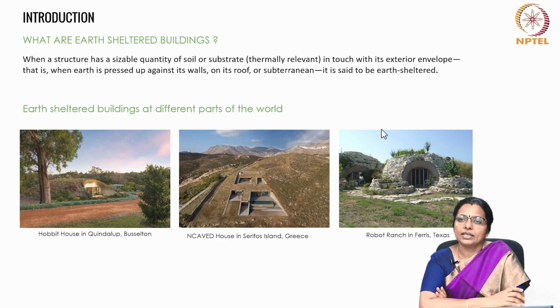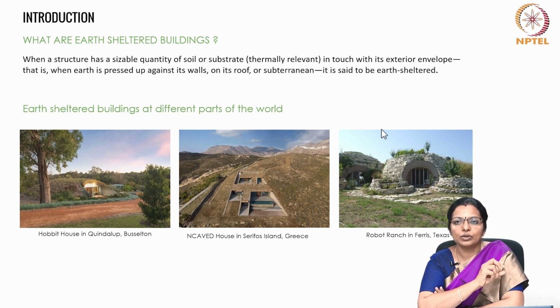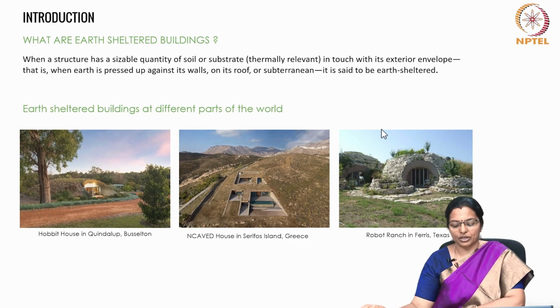Earth coupling is where concrete floor and sometimes even walls are in direct contact with the earth. In a well insulated, properly shaded house, this draws up the stable deeper ground temperature to the surface of the floor, which gives the house a head start in regulating its temperature.